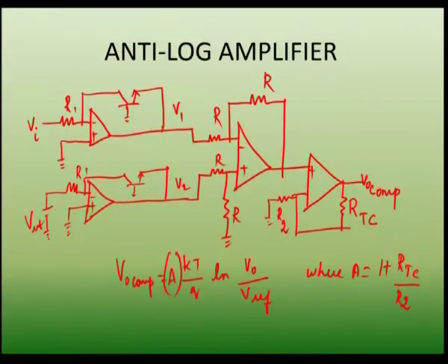So, we are considering that both operational amplifiers have the same IS, closely matched saturation current between these two logarithmic amplifiers. And so, the reference voltage is given separately here, and finally, the output of the logarithmic amplifier is temperature compensated.